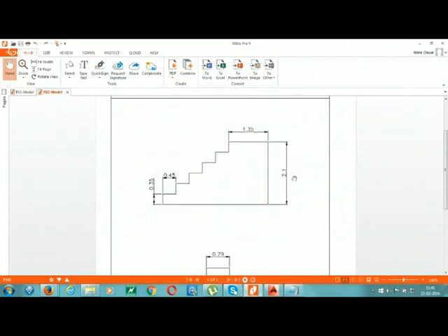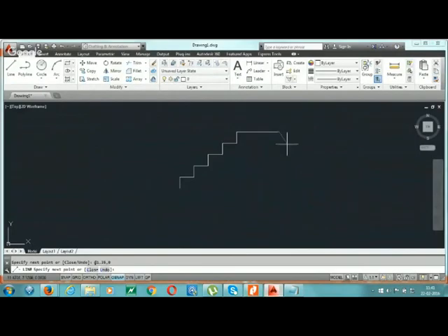Now our downward distance is 2.1. Then, we are in the relative method. Now in the relative method, going downwards, our y is negative, x is 0, comma minus 2.1. Enter.